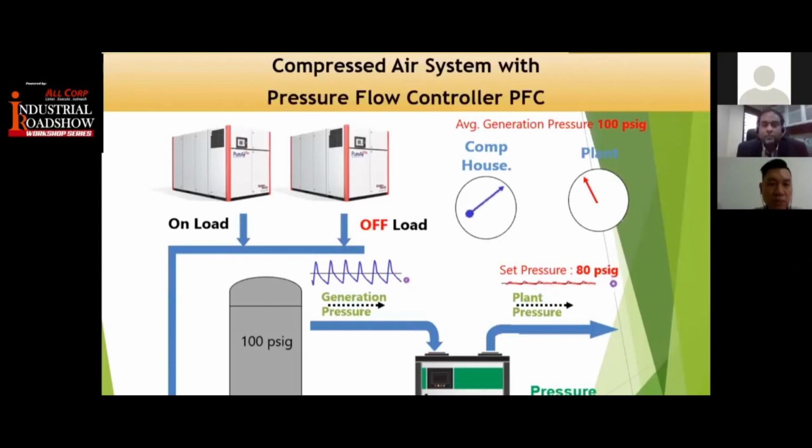Only one thing you have to be very careful about when you buy LED lights: make sure the LED lights don't have a very high percentage harmonics level, right? Nowadays there are a lot of light suppliers selling without telling the clients their harmonics level. If the harmonics level is very high, then their pricing is cheaper.